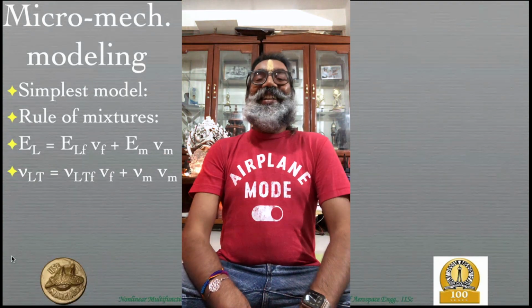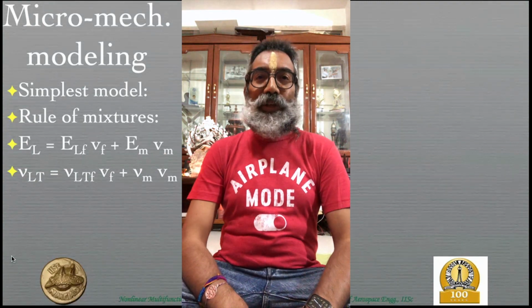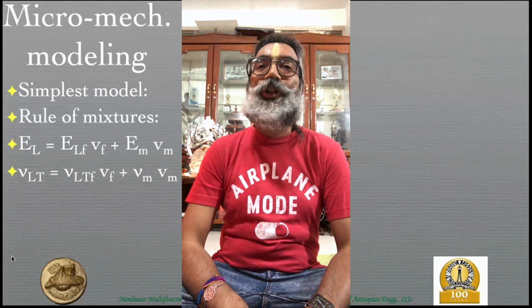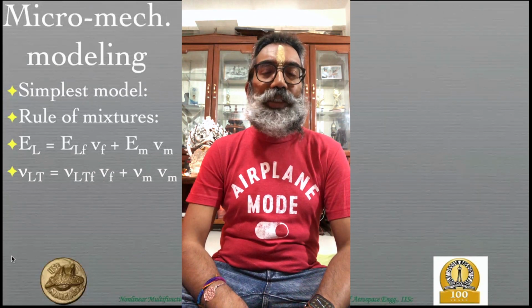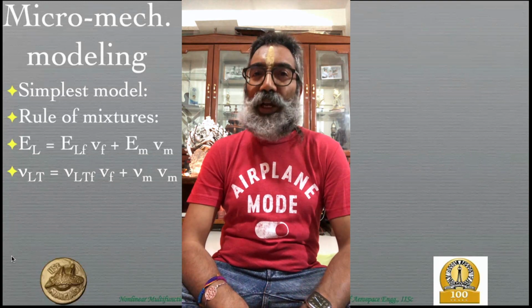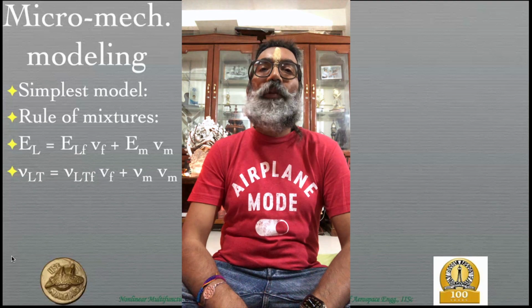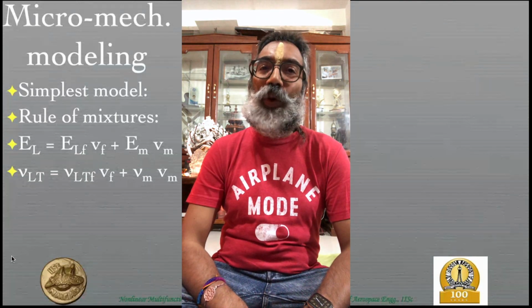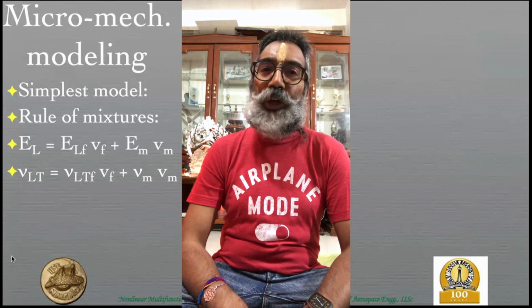Correct, yeah. So the reason for that is the limits on the bulk modulus and the shear modulus. If you actually see the shear modulus and bulk modulus, they can both be defined for an isotropic material in terms of the Young's modulus and the Poisson's ratio. E by 2 into 1 plus nu, for example, is the shear modulus.